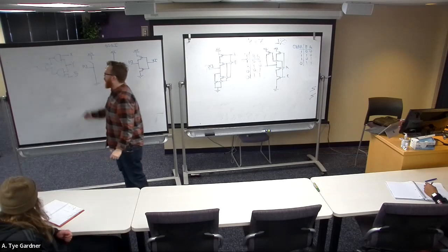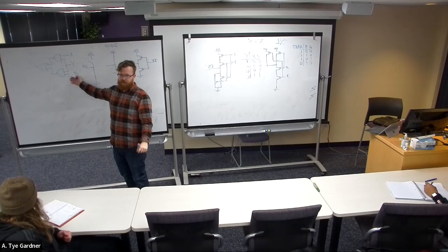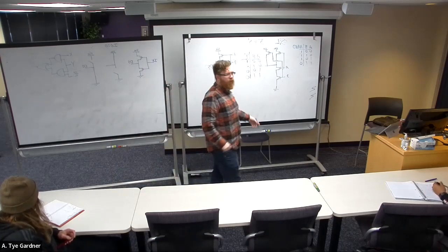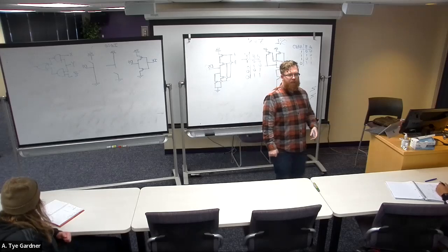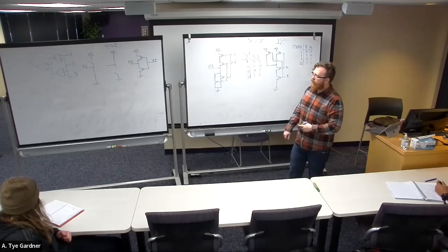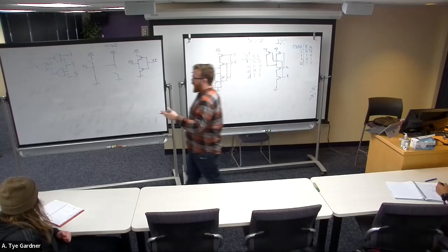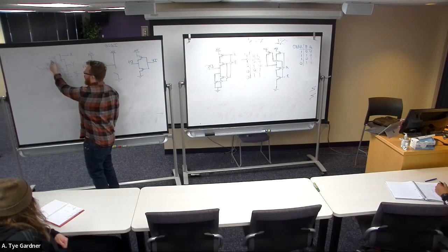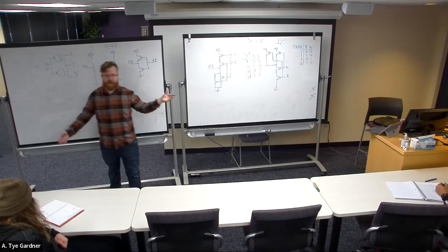And so then when you go and have a circuit, right, this is what we would call a canonical sum of products circuit. Canonical just means it's a uniform way of viewing things. That's sum of products. We would go ahead and do some bubble pushing, which, right, we would put 2 bubbles here and then slide one of them along each of those AND gates, and now I have nothing but NANDs.